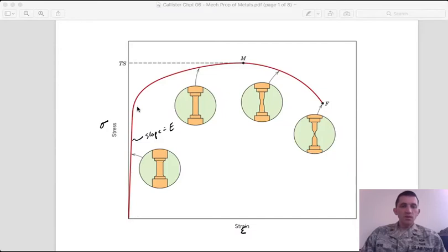At some point, the material can't withstand the stress anymore, and it starts to be permanently deformed. So we're stretching it beyond the point at which it could recover, and you get much larger degrees of strain. And as we'll see later on, this strain is not recoverable if you remove the stress.